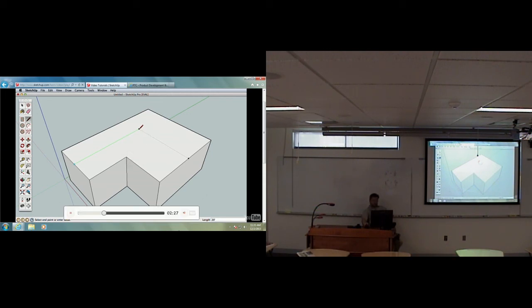Green direction, and SketchUp will infer to the new midpoint, telling you exactly how far to draw the first edge. Make sure you see both inferences and click to finish the first ridge. Then draw the second ridge to this midpoint. Now that we have both ridges in place, simply draw the lines where the roof will fold when we move the ridge lines.